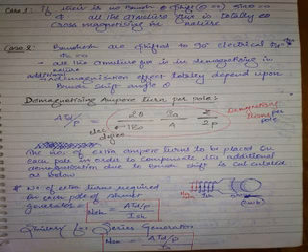Therefore, the theta region on the top of the armature and in the bottom of the armature is taken into account for the demagnetization. When the brushes are shifted in this manner, this theta, as well as on the down also the same theta. Similarly on the other axis, this theta as well as on the top theta. So this 2 theta as well as 2 theta region total, this 4 theta region is offering demagnetization.